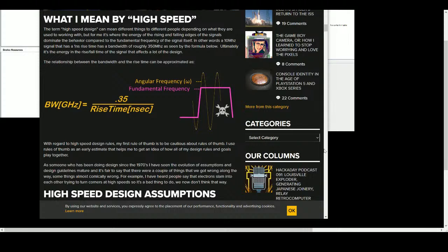And those fast edges happen because silicon switches very quickly now. We also want, most of the time we want fast edges. Because that allows. We want them to get there, but we want them to then die down quick. We don't want them hanging around for the next 6 nanoseconds. Right. So that comes back to the termination. You need a critically damped system.